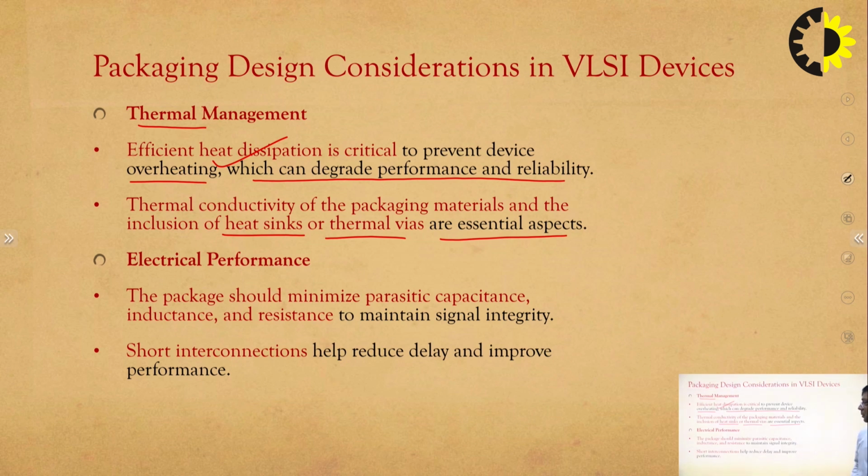Second is electrical performance. Now, the package should minimize the parasitic capacitance. As we know, parasitic capacitance is undesired capacitance which occurs, and the package should be designed in such a way that the parasitic capacitance is minimum. The package should have minimum parasitic capacitance, inductance and resistance to maintain the signal integrity.